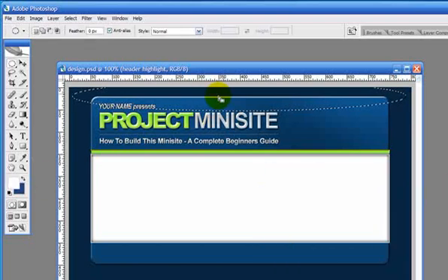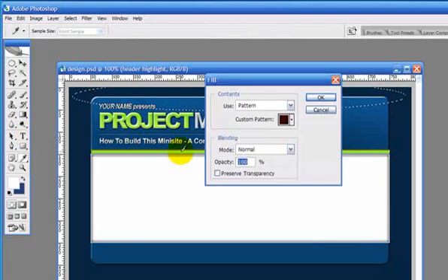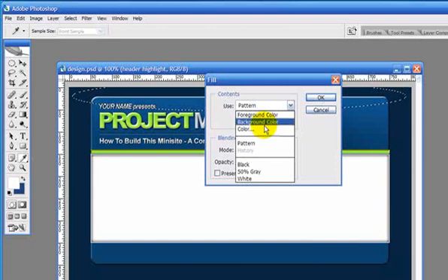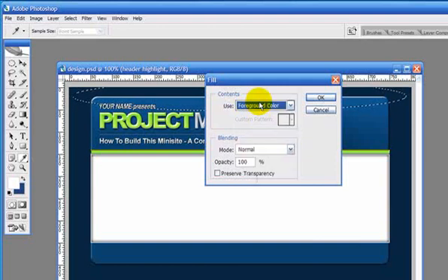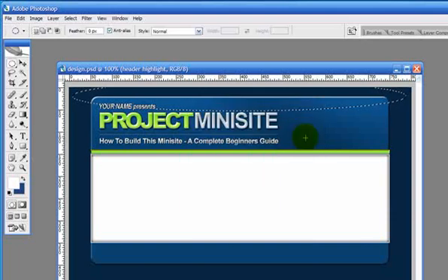Fantastic. And so the next thing we're going to do is fill this area here. Again, two ways we can do this. We can go to Edit and Fill, and make sure instead of pattern we have foreground colour selected there, so that will choose the white and fill this area with the white, and we can click OK there. Now just as a quick aside, a quicker way of doing this actually is, I'll cancel this option so it doesn't fill it.